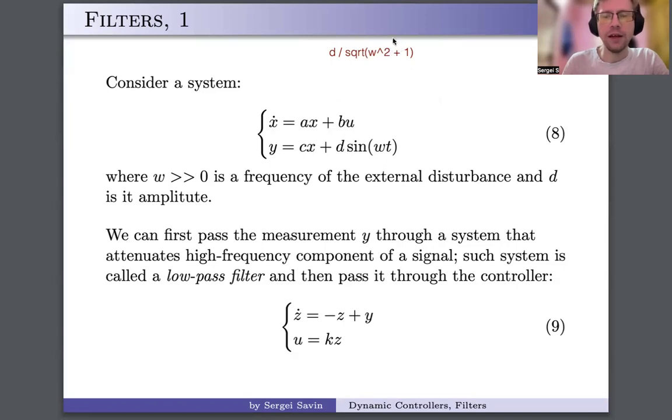Yeah. I mean, sorry, here I made a classical mistake. So 10 kilohertz squared is 100 million. Square root, back to 10,000. Sorry. So this signal is going to be basically 10,000 times smaller. Again, remember to transfer to radians per second. So it would be, roughly speaking, 10,000 times smaller.